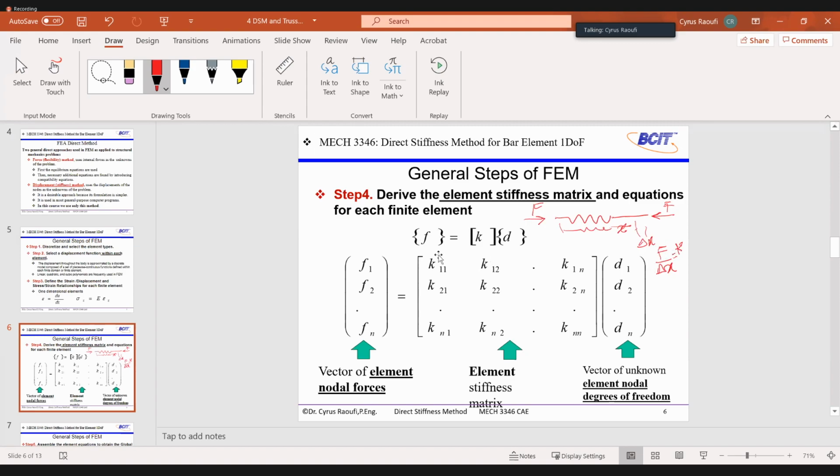And if you look at this equation, we have F equals K times D, and D is displacement. Now, this equation, which is the first simple scenario in terms of geometry and loading, which is one directional only for a spring, looks the same in terms of the components. We have force, we have displacement, and we have K. However, if you look at this equation, I put some brackets over those parameters, because in finite element analysis, we do not have only one node or one element.